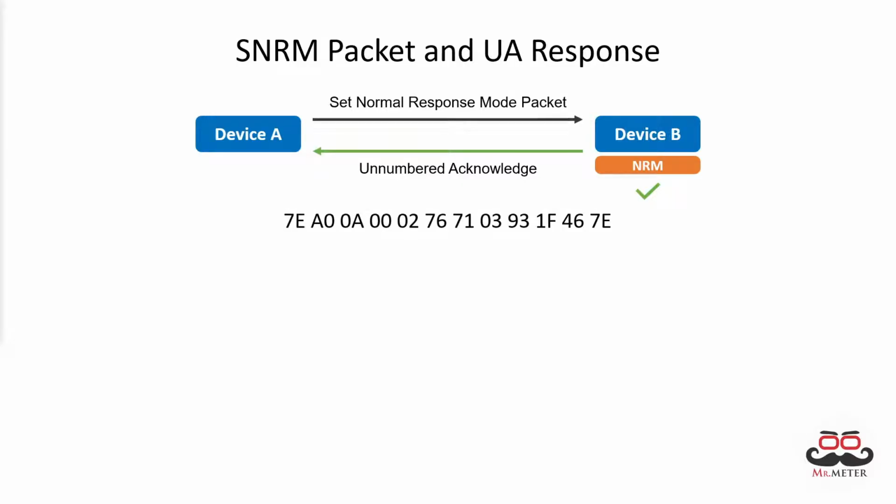This is a sample packet in which the client is connecting to an electricity meter over a TCP connection to a gateway which is transmitting data transparently to a meter from the client. This is an example of a connection-oriented communication over a connectionless communication in which a virtual circuit is formed before transmitting data.